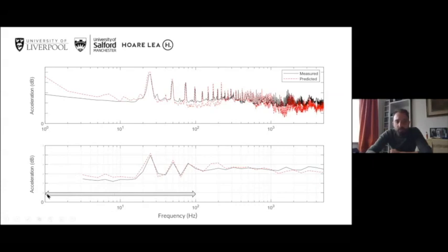And now the frequency range we're interested in for tactile vibrations, which humans can feel, is in the range 0 to 100 hertz. But in this case, we're only really interested in 10 to 100 hertz, because the compressor operates at such a speed that it's not really exciting any vibrations below 20 hertz at all, really.